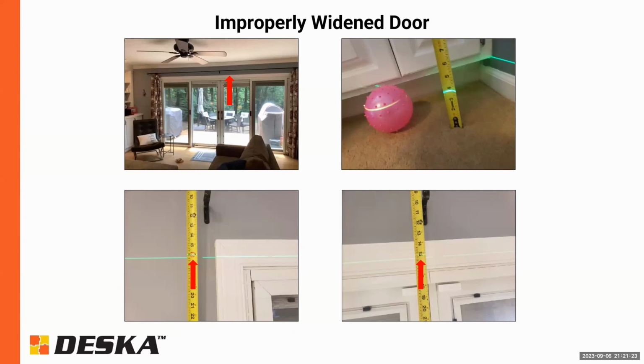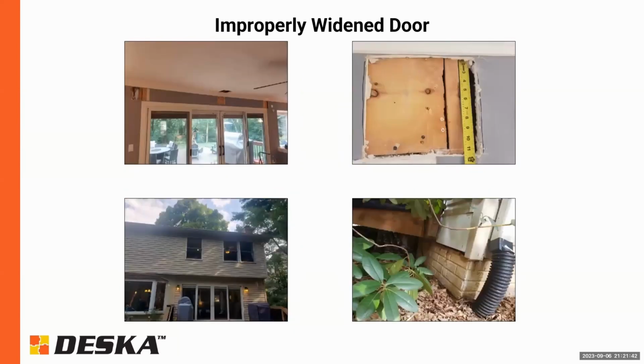We also put a laser level on the floor above, and essentially we're getting about an inch and a half or so of settlement of the floor as well. So all of these signs lead to a sagging issue of the beam above. And so the next step in this case, we had the owner remove some sections of drywall and determine in this case there was just a 2-ply 2x12 here supporting this.